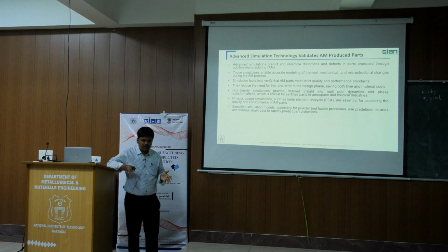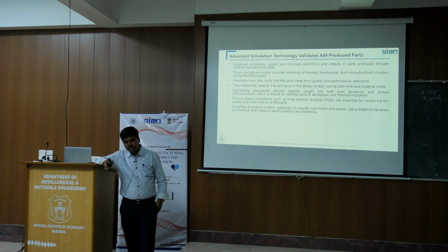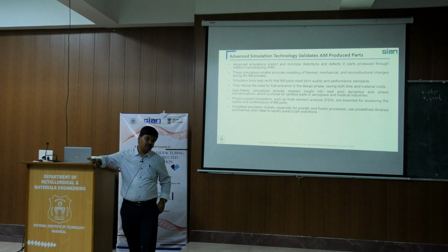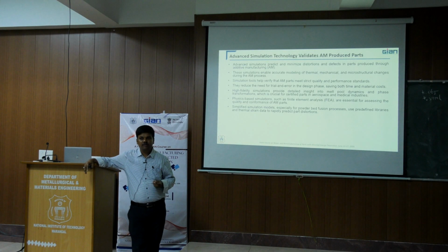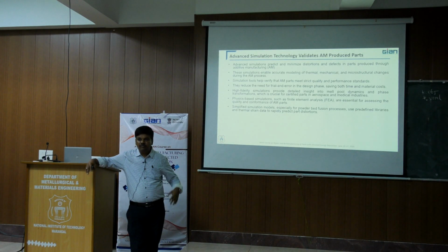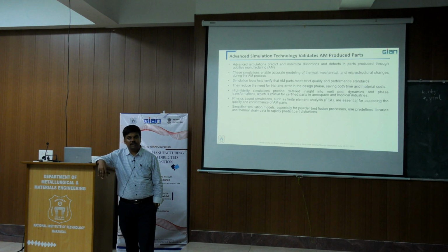But when you consider the laser powered DED process, in the welding process almost 100% of the material is melting and deposition is taking place. With laser powered DED, only 40 to 60% of our powders are melting and solidifying, because of the reflectivity of the materials, the absorbability of the materials, and how much loss. Here the melt pool formation is different from welding, and compared to welding, rapid solidification takes place in the laser DED process.